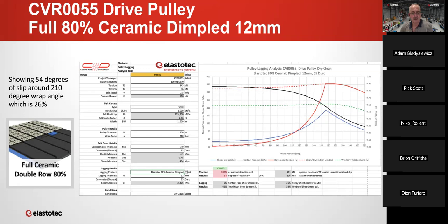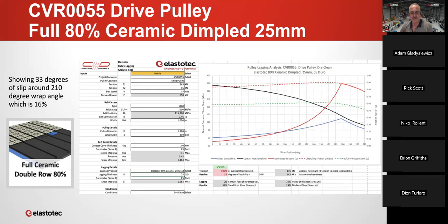And then if we look just quickly at the 25mm version, the extra thickness has reduced the localized slip from 54 degrees down to 33. It's also reduced the shear stress from 206 down to 143, and we don't have any fatigue issues.